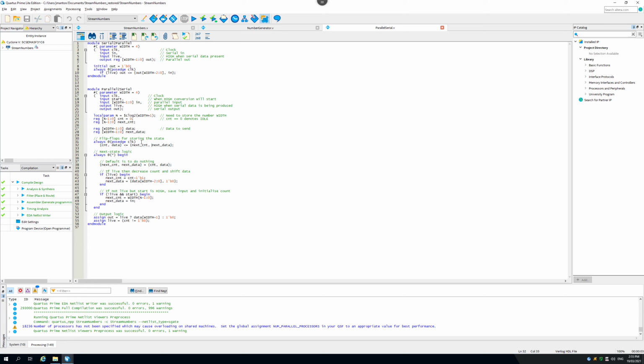Here are our flip-flops, same as always. For each state register, we declare another register for the next value it's going to take, and our flip-flop code simply assigns the next value to the current value. So always use this same format here. Then I just need my next state logic and my output logic.